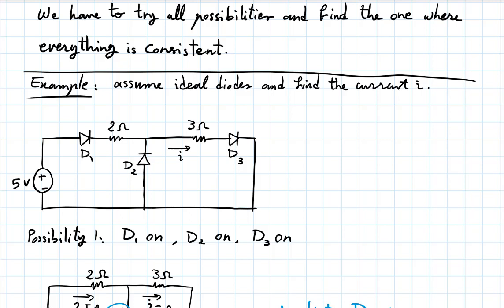When you look at a modern-day circuit solver, as an engineer, you might design a circuit using this kind of insight, with this kind of simplification, these models with various degrees of sophistication, because they would give you the general behavior. But once you have designed the circuit, and your circuit might have 20 diodes in it, now you want the exact numbers. You would put it in a simulator for which the code has the exact models from the manufacturers representing the characteristics of each element, including the diodes, and would solve the system of nonlinear equations for all the unknowns. So these are all done routinely. And of course, they are done by nature automatically every time your circuit does something, right? So they're happening in your devices all the time.